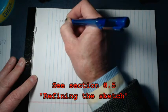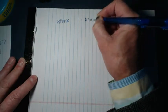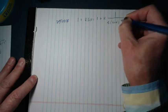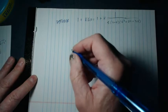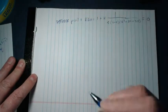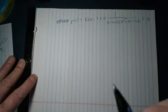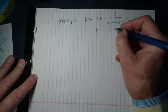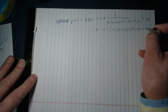We can talk about that there's a polynomial in S, let's start here. 1 plus KGH is equal to 1 plus K times 1 over S plus 4, S squared plus 8s plus 32. So that's a polynomial in S that we can set equal to 0. So we're going to set that polynomial P of S equal to 0, and this is going to be K is equal to minus 1 times S plus 4, S squared plus 8S plus 32.